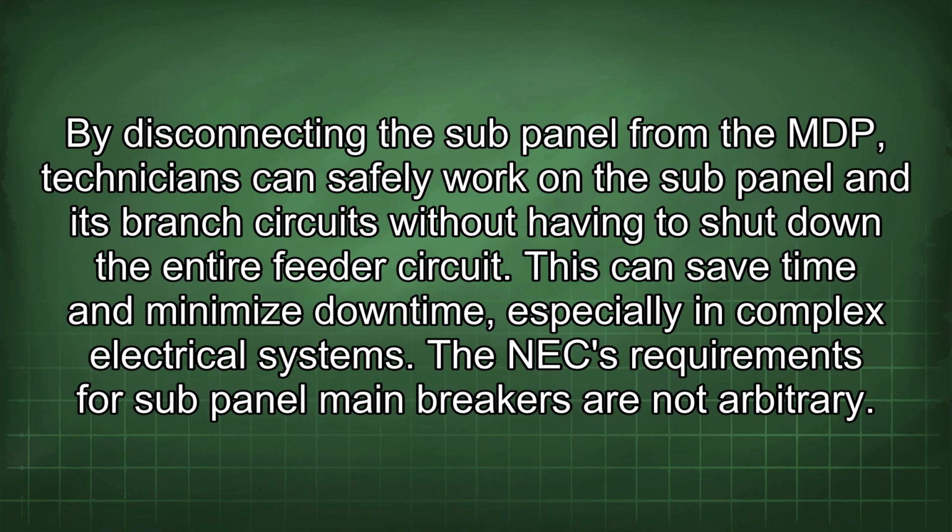By disconnecting the sub-panel from the MDP, technicians can safely work on the sub-panel and its branch circuits without having to shut down the entire feeder circuit. This can save time and minimize downtime, especially in complex electrical systems.